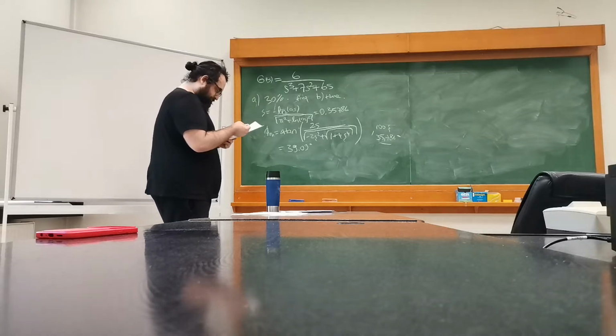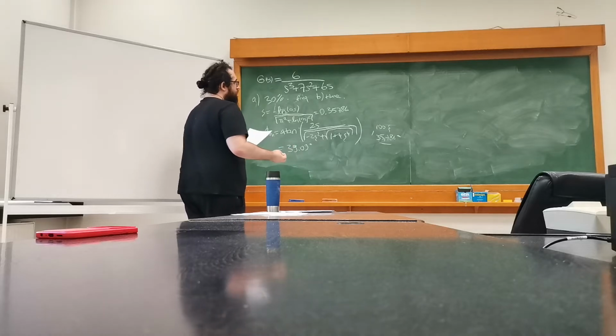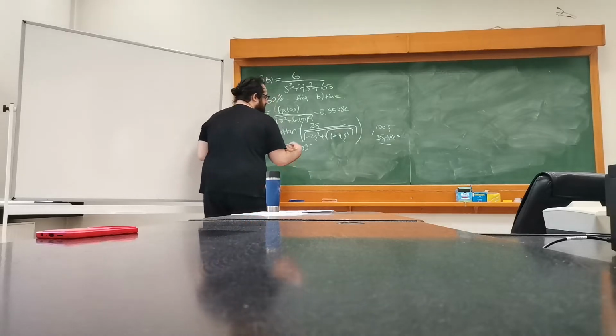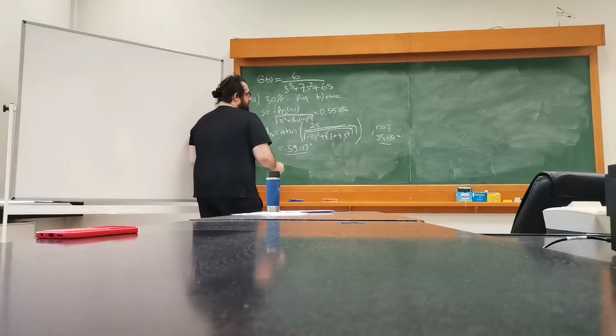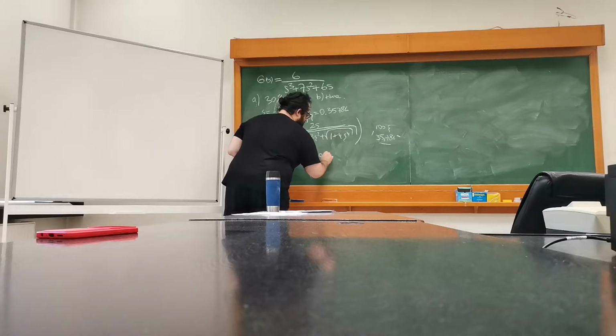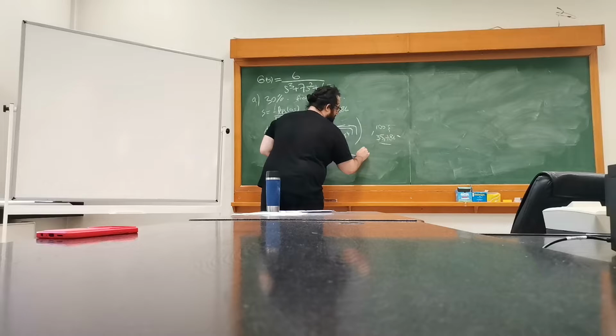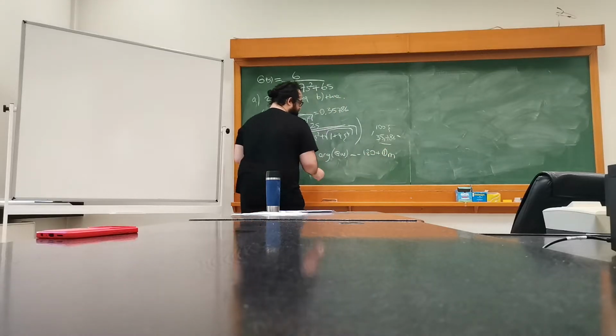It really depends. Once we have that, the only thing we look for is the angle condition. So if we have minus 39, then the argument of the system should be minus 180 degrees plus phi m. Therefore, we look for this specific frequency.